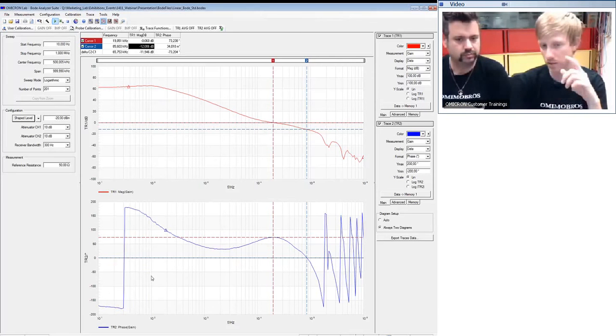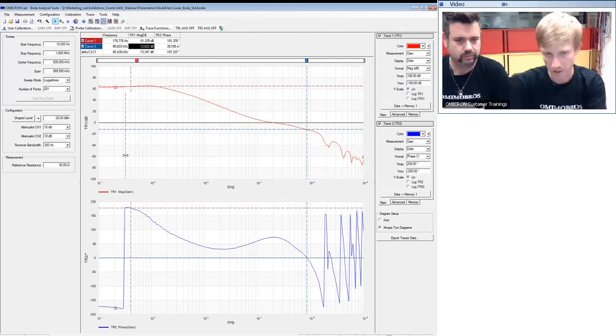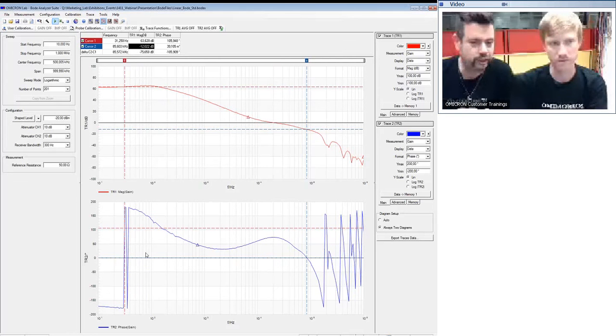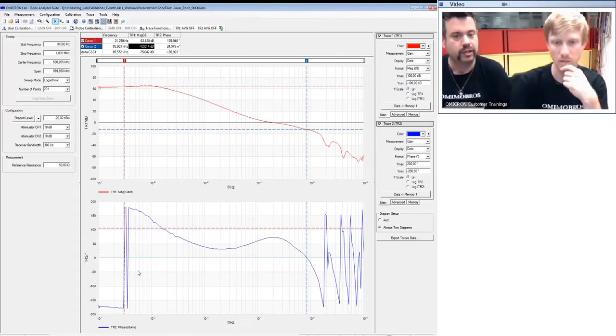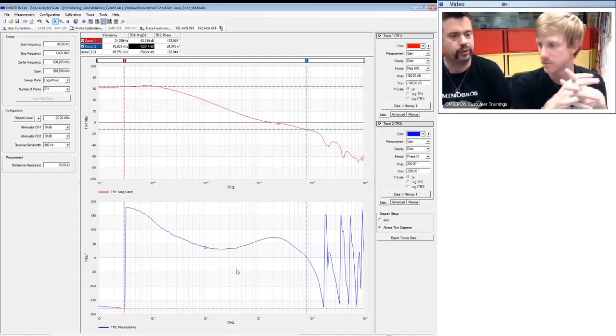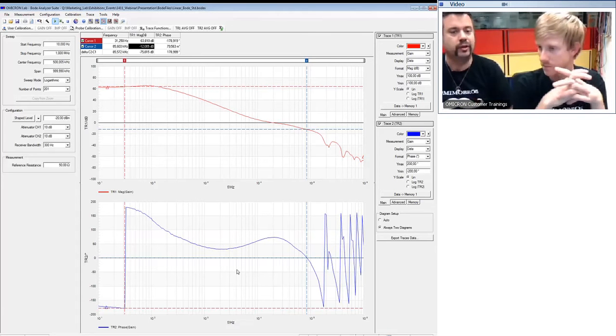But Bernhard, something many people are confused with: what happens with the phase at this 10, 20, 30 Hertz? What is happening here? Why is the phase jumping that much? Well, in fact, the phase is not actually jumping. What's happening is that the phase shift of a good loop can start at minus 180 or plus 180 degrees. And the problem is, when you display a phase, usually you display it only between minus 180 degrees and plus 180 degrees. And as a result, plus 181 degrees is minus 179 degrees.